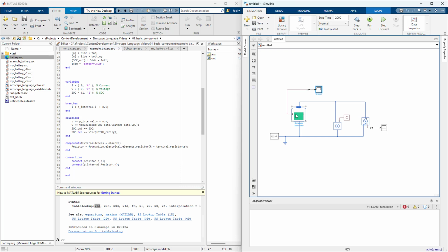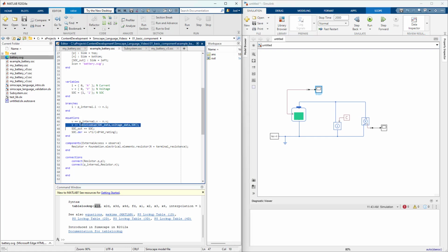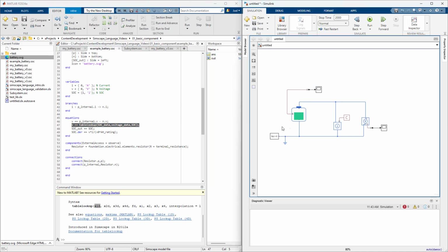But I think 90% of the time, if I'm doing something in Simscape, it's really just that I want a nonlinear mapping that I can define. So I use this for building custom saturation effects all of the time. That's a really common one in magnetics, where I have to worry about nonlinear thermal effects on systems. That's where I do it the most. I work in power electronics, so that's why I worry about that. On my side, we don't worry about the battery too much. We treat it like a constant source half the time.